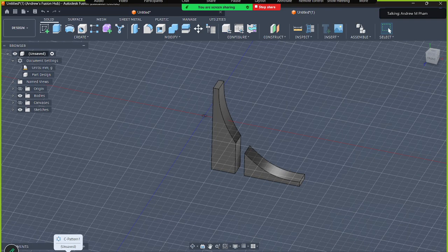The circular pattern is copying the body, so we're modifying the body now, and then when we pattern it again, or roll this forward, all of the changes that we made will be applied to it. This might be different if you were patterning a feature, but in this case, because it's a body, it'll copy everything.